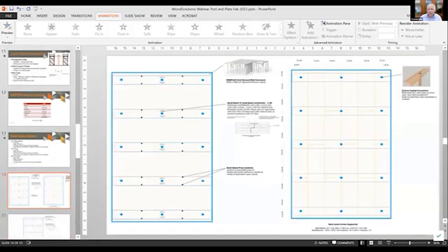So you can just imagine the first thing in the construction process is you lay down your band beam on top of your columns, and then you support it. Then you overlay your floor, which goes perpendicular to the direction of the band beam, and that is connected together to increase the depth of the beam, as well as acting as the floor between the beam. And it amazes me, but what we're doing here, and it comes back to this fundamental likeness between timber and concrete, is the compressive strength of timber is pretty much the same as concrete, and all the tricks that we can use with concrete can be overlapped onto timber.